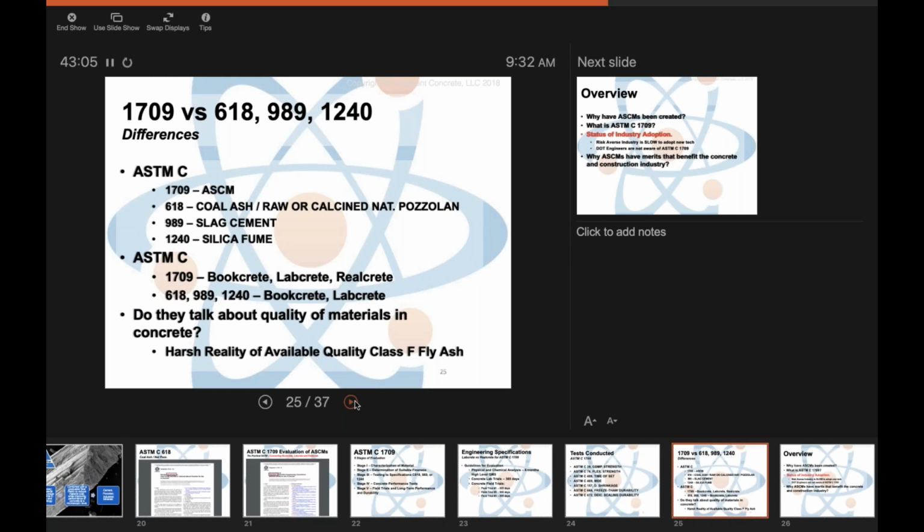So things like you have to have a minimum of 70% silica-based material, and that can include some alumina and I believe some iron. Then there's also, you can't have more than 34% retained on a number 325 sieve. You can only have a maximum of 5% alkalis, and if you do have more, so on and so forth.